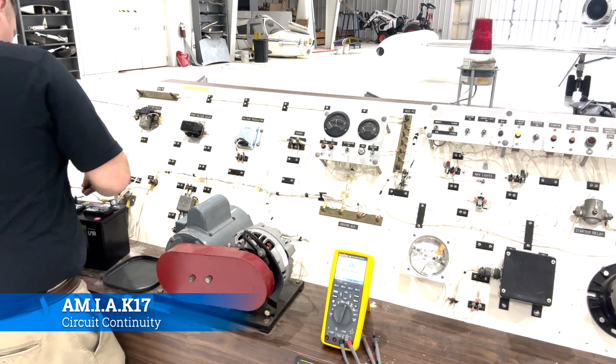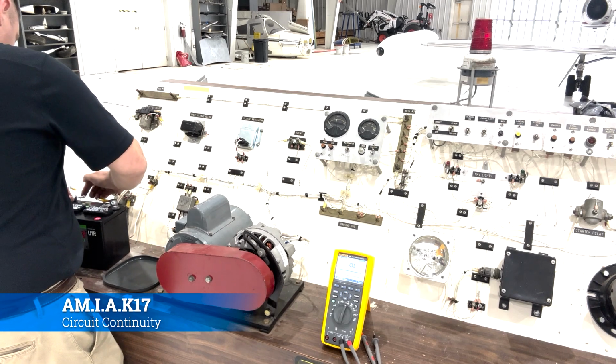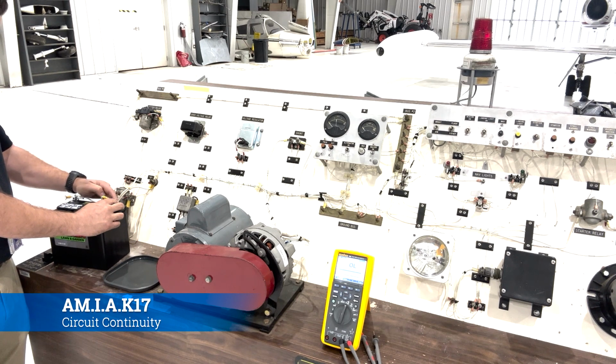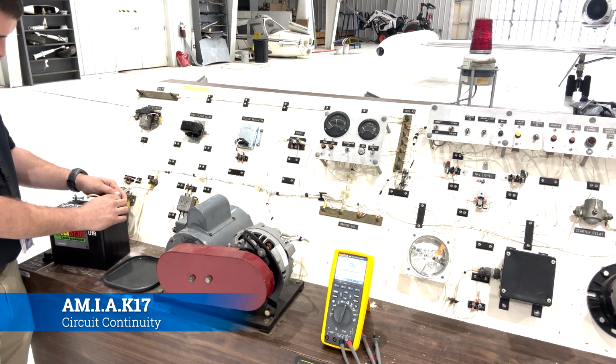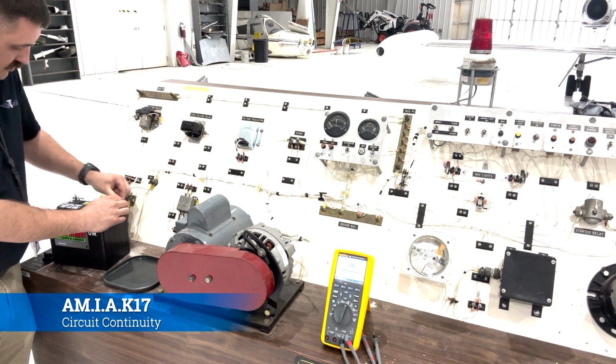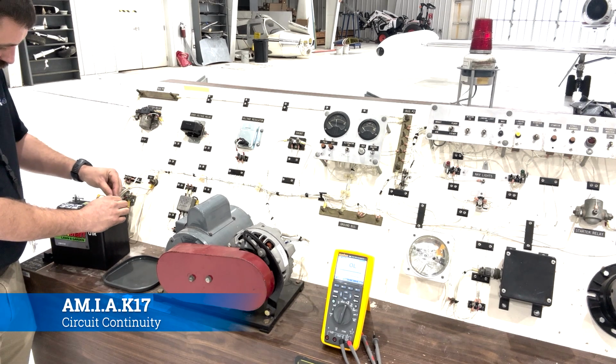Now, there are situations where you're going to want to troubleshoot power. That is something that we'll cover later on. For right now, don't worry about it. For your continuity checks, make sure that the battery is disconnected, the airplane is not running, and it's not connected to ground power. Those are the three places that you can get electrical power on an aircraft. You want to make sure they're all disconnected before you start shooting wires, because if there is a fault on the aircraft and you ground it out, you're going to get an arc, and those arcs can be pretty devastating, and you don't want your hand to be the one that gets devastated or electrocuted.